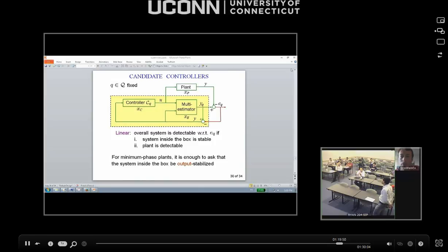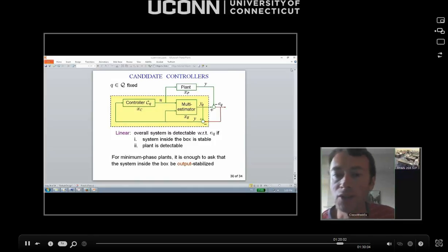I'm not sure. Are you assuming away the difficulties, or if drop time is very long, could anything happen during your switching? Personally, I would not use a large dwell time for a nonlinear system unless I'm sure that its solutions are somehow well behaved, that I have some compact sets which they will not leave, because otherwise my transient behavior will get worse as my dwell time is increased.